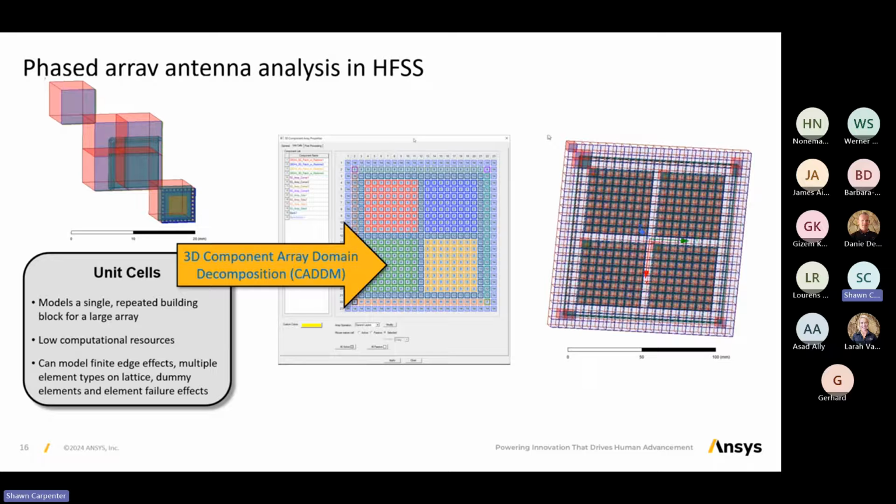Right. And so we've developed a technique called 3D component design decomposition or domain decomposition, which will leverage unit cell simulation models and then put them into an iterative solution with a collection of other unit cells to give you very quickly a very accurate model for the array that will give you wideband feed point characteristics, S parameter characteristics that are appropriate for active array considerations, active element considerations, and then would enable you to do beam steering studies so that you could drive any excitation against this that you want to look at: single beam and multi-beam simulations, beam nulling, right?